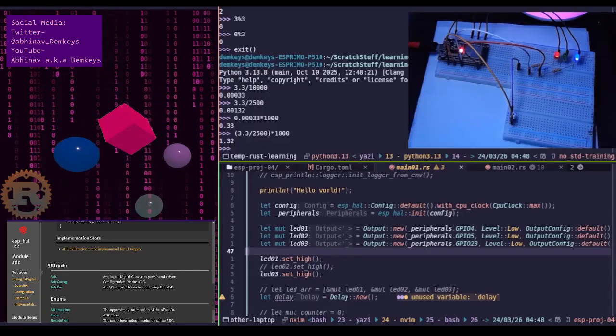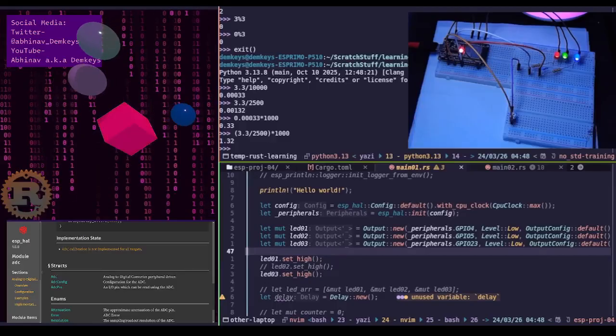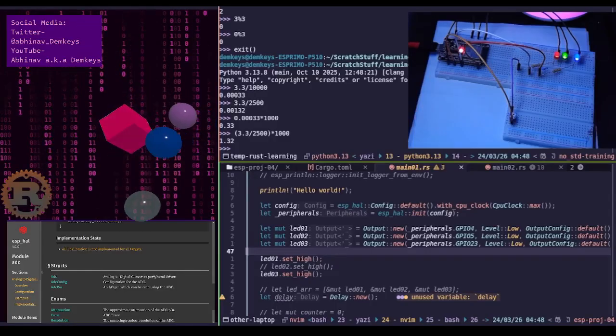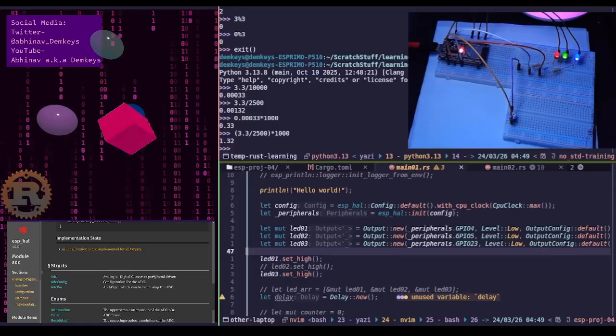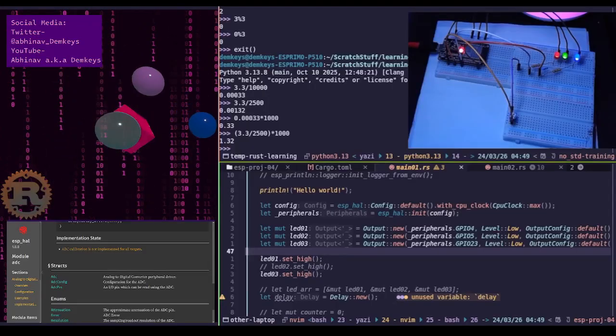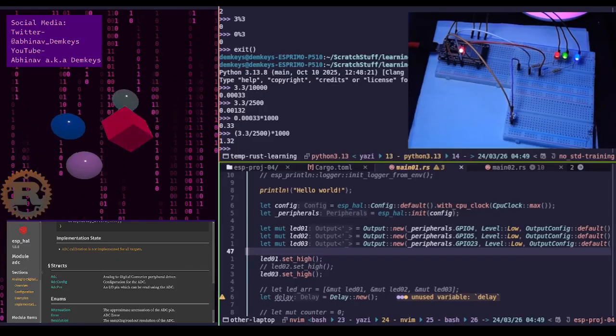If the ADC pin had low resistance, it would leak current to the ground and your voltage signal would sag, giving you an inaccurate reading. Why this matters for your Rust code? Okay, yeah, that's fine. It's talking about the ADC readings.